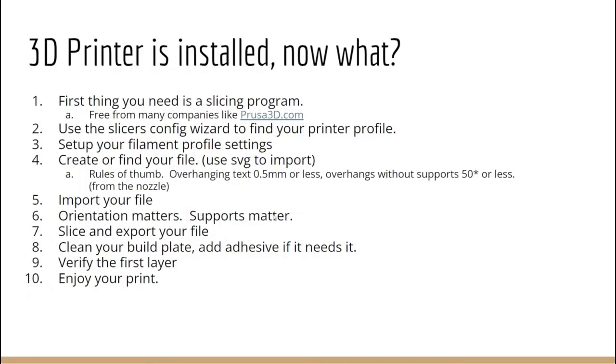And some of the important pre-flight checklist things, you need to make sure your build plate's clean, whether it's from the last print or even, I had one of my printers come in from the factory. There was some kind of film on the plate, and I just assumed it's brand new, it's from the factory. I plug it in. I couldn't get prints to stick. Started doing all the troubleshooting of all the things that are proper to find out that the build plate just had some film on it that I couldn't feel, and the IPA, the alcohol that I used to clean, it was just thinning the film. It wasn't actually removing the film. So we'll talk a little bit about that.